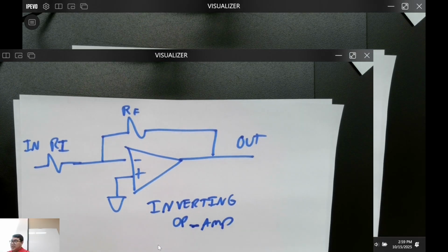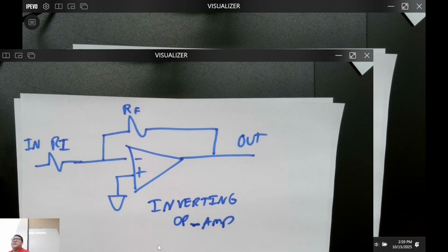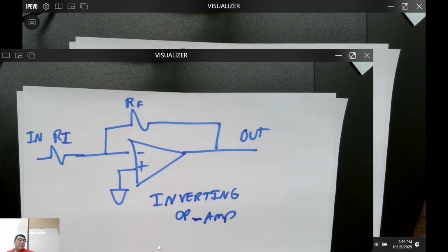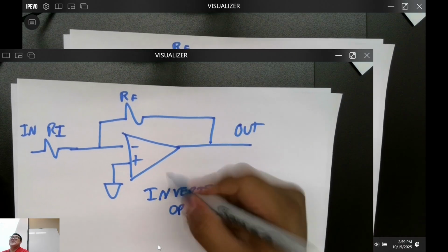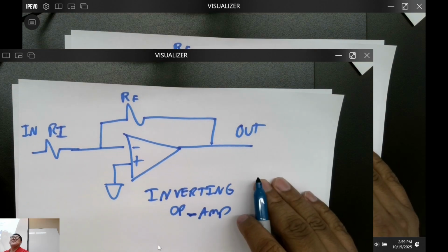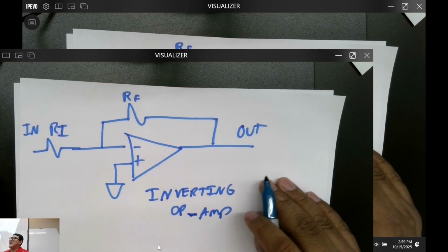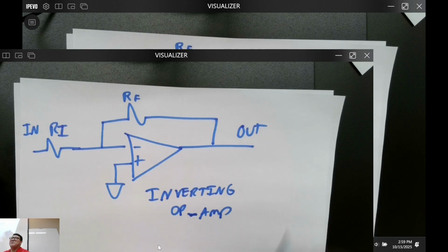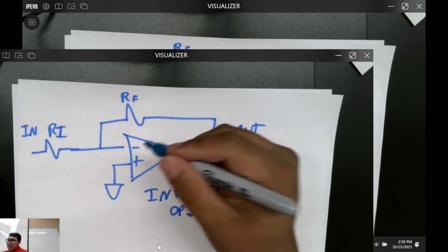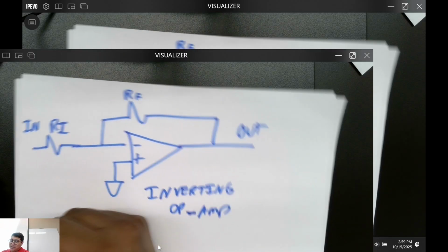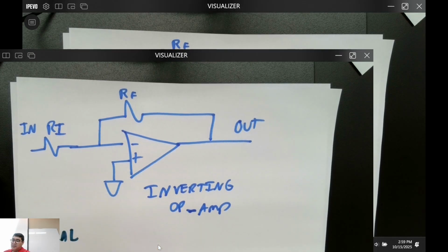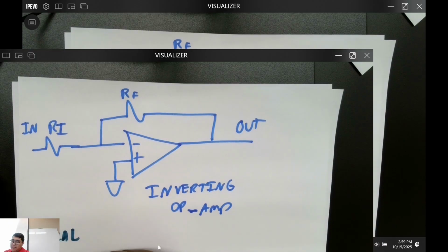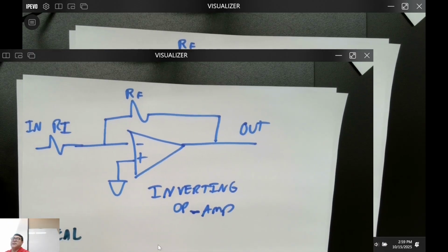So the way you solve this circuit, have they gone over the proof, or do you want me to prove it in class so you can copy this home? How do you solve for this voltage? What do you know about KCL? Or before that, remember how in an ideal case, V plus of the op amp wants to equal V minus, so that there's some type of equilibrium.